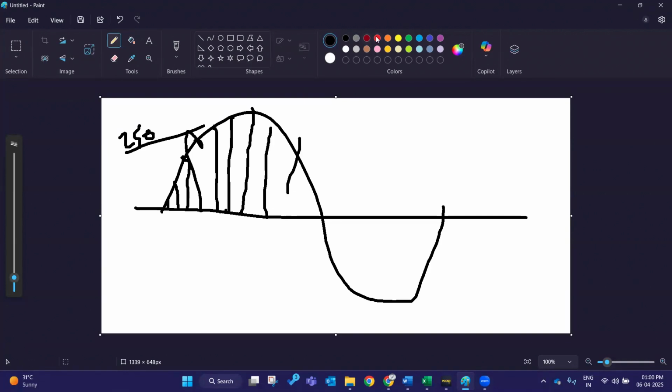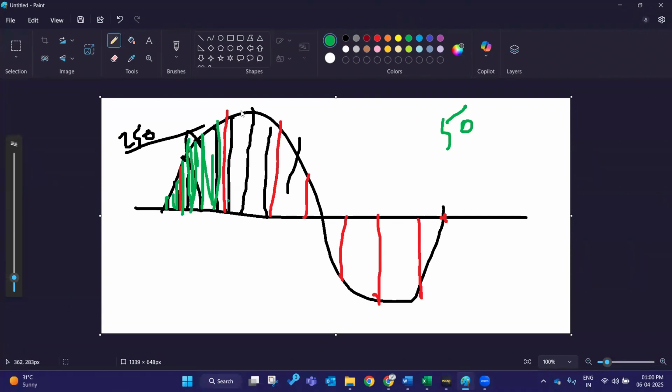But when you place 2000, starting from here, another 2000. The channel plot step will plot at every 2000. The same goes for the solution time step. Giving 50 microseconds means every 50 microseconds, your solution time step will be plotting the graph, right?